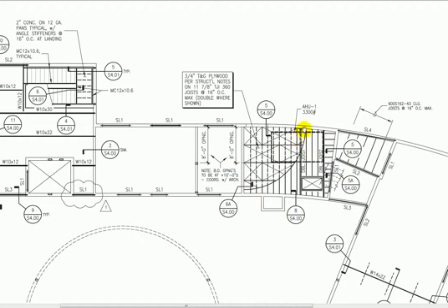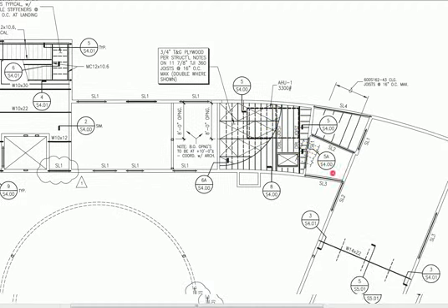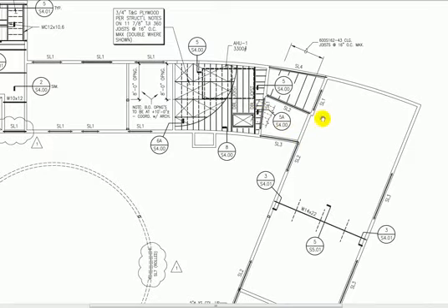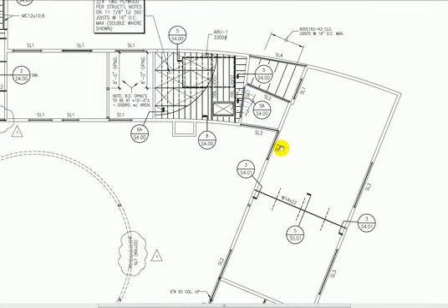So you can see, again, it's kind of cut away, but I see AHU1, 3,300 pounds. So this looks like it's supporting an air handling unit. Double joist, just a little wood mezzanine. I walk around here, I see SL2. Well, I know that these are walls, so I'm thinking that's probably a steel lintel, and I'll find a schedule somewhere that talks about SL2s, and it should be titled steel lintels.